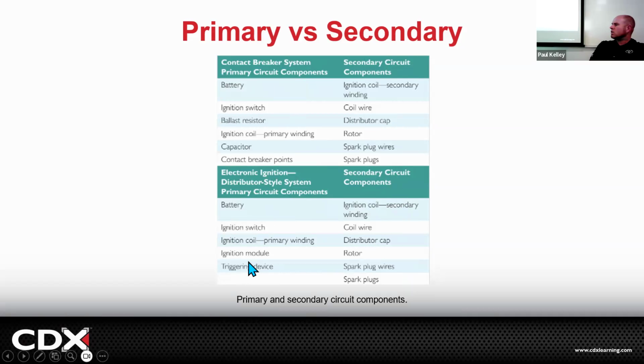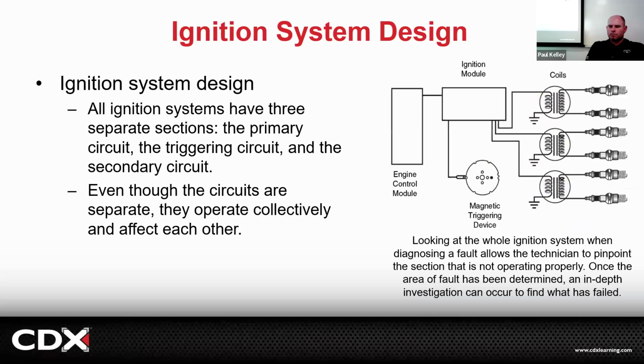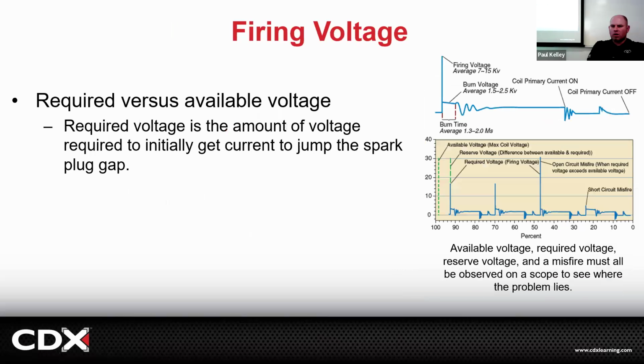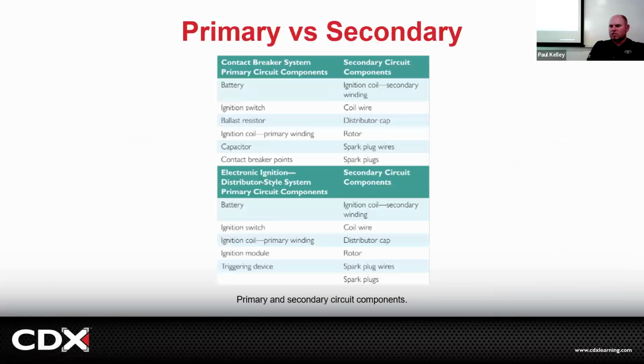So we went with that triggering device that, remember, if we looked at the triggering device way back here, there's no contact here. It's just through induction. Induction doesn't wear stuff out. Making something open and close over and over and physically move is going to wear stuff out. So when it's induction like that, it's just going to be much less of a wear item, much more reliable over time, but harder to diagnose.